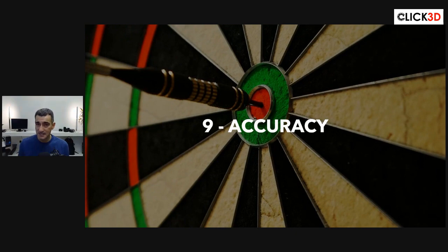In some cases, photogrammetry would be the clear winner, especially if you're doing a very small object and getting below a millimeter or two accuracy. While in other areas where it's really big or medium sized, a few hundred meters, sometimes the scanner will probably do a bit better. At least that's what I found anyway.